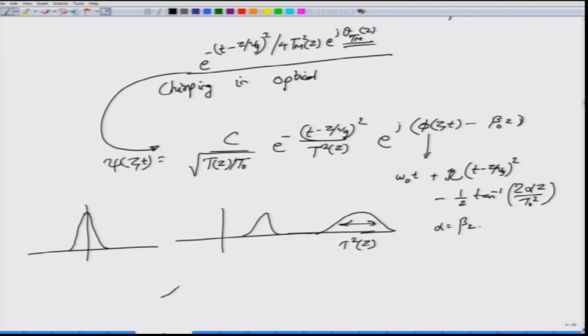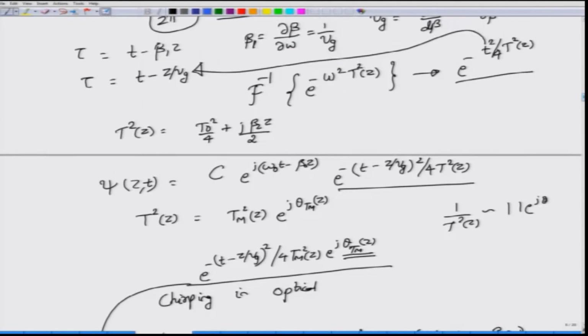you will see that, first let me draw the pulse envelope, now let me fill up the modulated waveform. So, the frequency of the carrier is actually increasing. So, this phenomenon is called chirping. You can look at the assignment for more details, for some careful details about the mathematics involved here. I have just kind of given you the intuitive picture.